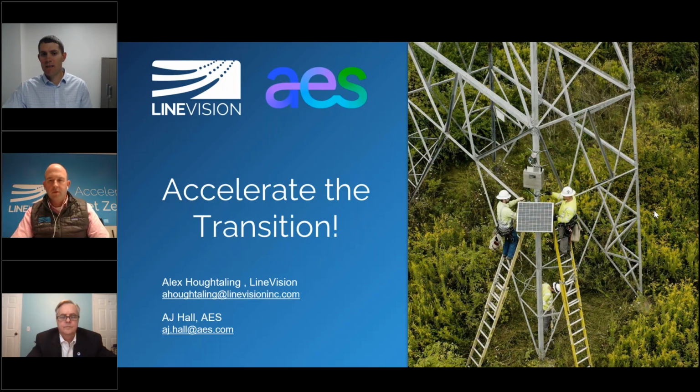And in interconnection, I think one step is it can improve interim deliverability. A lot of projects can connect to the grid, but they might not be able to get full capacity deliverability until transmission upgrades or network upgrades are built. You can use GETs, like Alex mentioned in the reconductoring scenario, for 2-3 years while you wait on transmission build out to be able to deliver more of the capacity of your renewable installation.